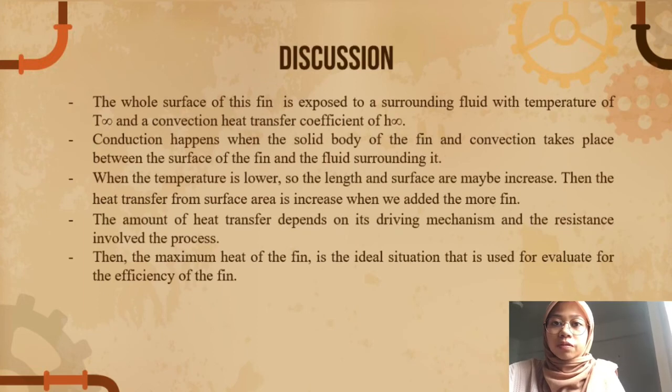The whole surface of this fin is exposed to a surrounding fluid with temperature of T infinity and a convection heat transfer coefficient of h. Conduction happens in the solid body of the fin and convection takes place between the surface of the fin and the fluid surrounding it. Next, when the length and surface area are increased, the heat transfer from the surface area is increased when we add more fins.